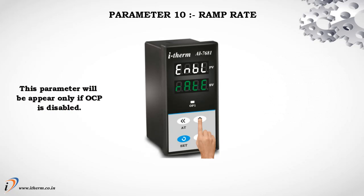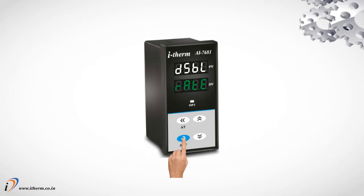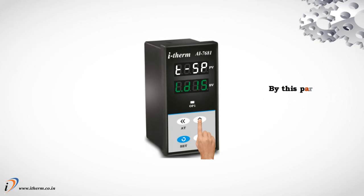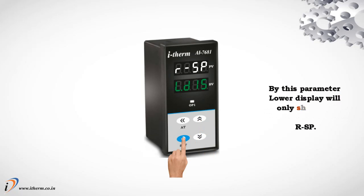Parameter 10, ramp rate. This parameter will appear only if overshoot control point is disabled. When enabled, user can set the desired ramp rate in user list. When disabled, this parameter will not appear in user list. Parameter 11, lower display message. This parameter will appear only if ramp rate is enabled. By this parameter, lower display will only show the target set point, T set point, value. By this parameter, lower display will only show the ramping set point, R set point.